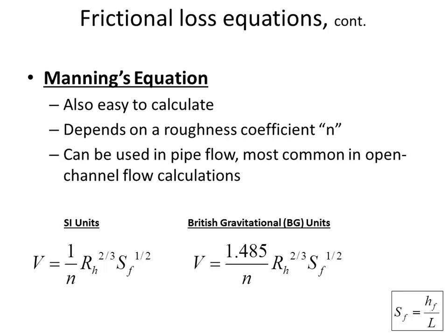So, for example, you might have an N value for grass where the water is moving at a low velocity, or there could be a different N value for grass where the water is moving with a high velocity, because whoever put that table together knows that grass that is standing upright would give you a different amount of resistance than when the water starts moving fast enough that it's pushing the grass over, then the N value will be lower. There will be less resistance. And so the N value doesn't really change as you're solving the problem, but sometimes you'd use a different N value depending on the conditions that are described in the problem statement. And we'll see that through the semester.